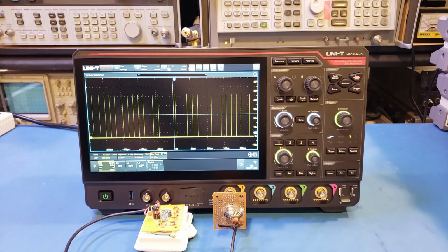To solve this problem, modern digital scopes often include the so-called segmented memory mode. The idea here is instead of using a single chunk of large sample memory, the memory is divided into smaller segments or frames. The main difference is once triggered, the oscilloscope will only fill the next available segment instead of the entire sample memory. And once a segment is filled, the oscilloscope will stop capturing and rearm the trigger until the next trigger event occurs. So in this way, even if the events of interest are few and far in between, you can actually capture all of them because the events will be individually triggered and captured into their own memory segment.